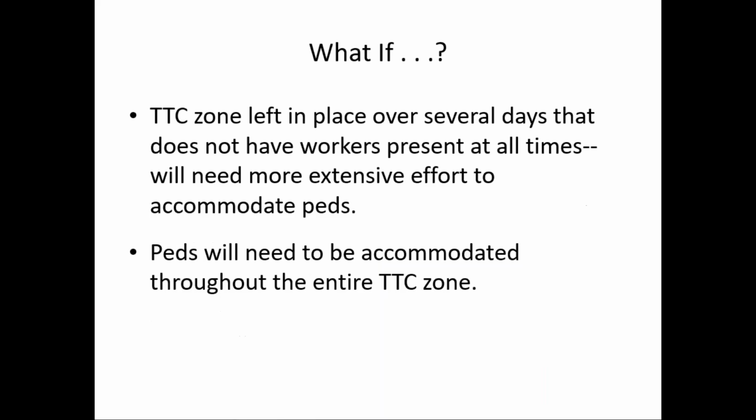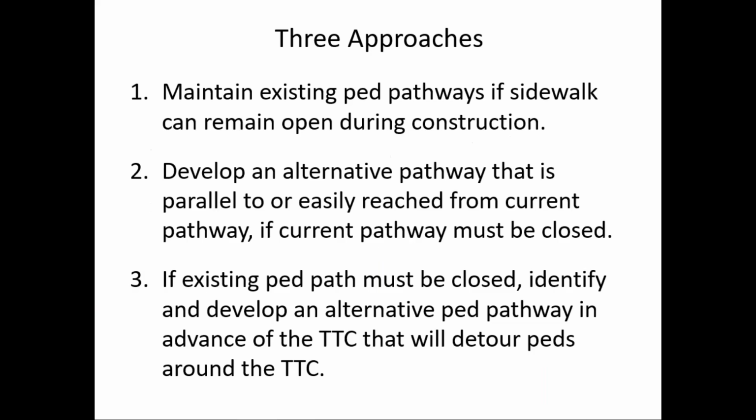But many work zones are left in place, of course, over multiple days or even weeks. And there's not going to be workers present at all times. So we're going to need more extensive efforts to accommodate pedestrians. And that's what we'll talk about now. There's three approaches. We can maintain existing pedestrian pathways if the sidewalk can remain open during construction. Maybe it's narrowed or something like that, but we can maybe use the existing pedestrian pathway. That's what we should strive for, if possible.